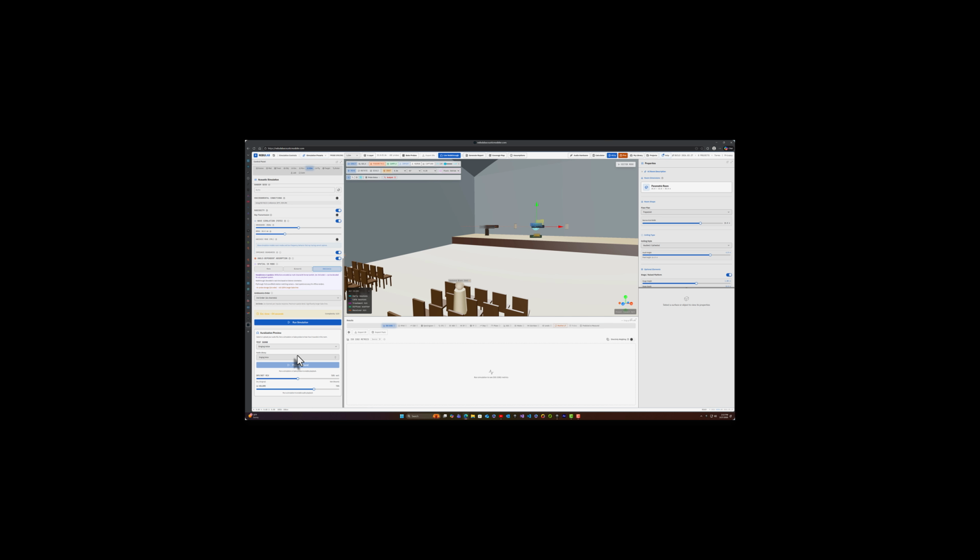Higher probe density generally improves spatial accuracy, but takes longer to compute. Lower density bakes faster, but with less spatial detail. For this example, we'll choose a conservative 2-meter probe spacing. Now the final step, bake the probes.